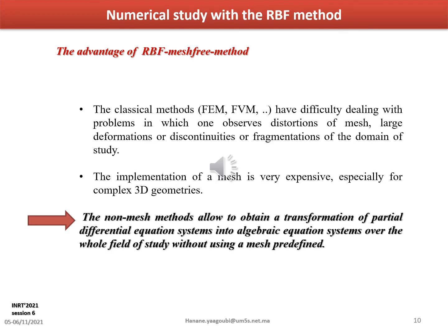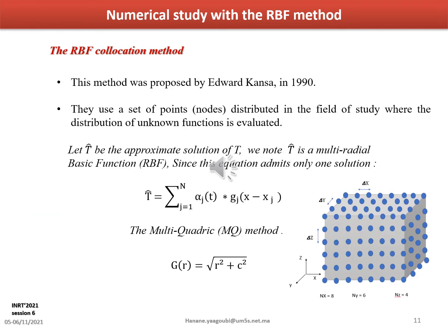So what is the advantage of the radial basis function meshfree method? The classical methods, as you know, finite element or finite volume methods, have difficulty dealing with problems in which one observes distortion of mesh, large deformation, and discontinuity or fragmentation of the domain of study. The meshfree methods allow transformation of partial differential equation systems into algebraic equation systems over the whole field of study without using a predefined mesh. So we use a set of nodes distributed in the field of study where the distribution of known functions is evaluated.